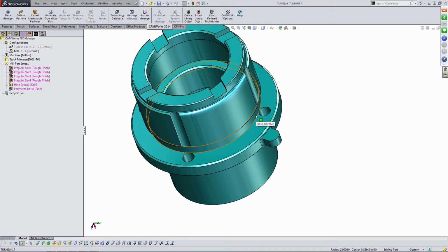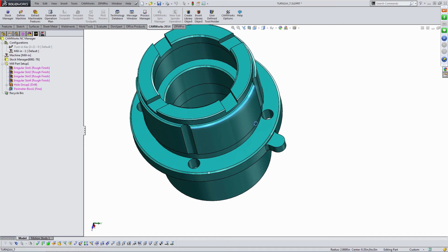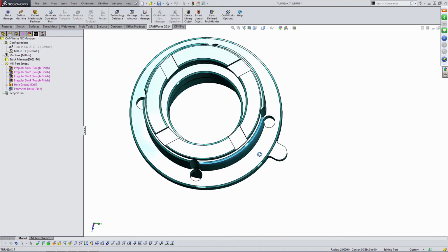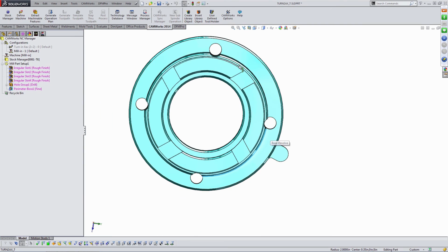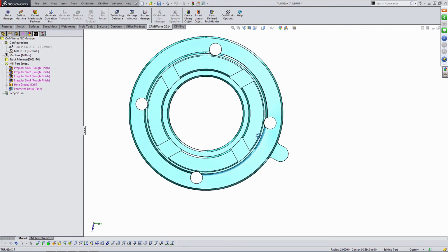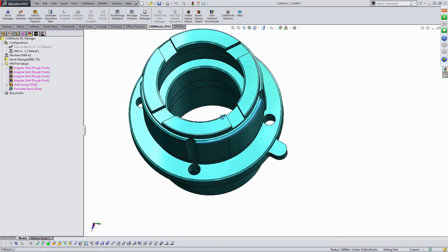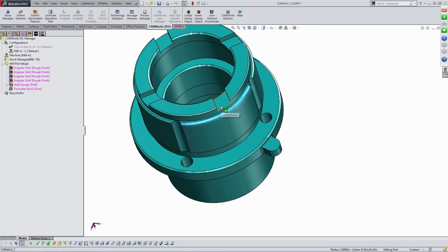I could bring in an end mill and just swoop it in, kind of C-shaped, or I could just circle the whole part. That would be very easy to program. Or I could bring an end mill in straight in and just kiss it. Luckily, this is kind of hypothetical, and I don't know which would work out the best, so maybe I'll just program the kiss. I like that.